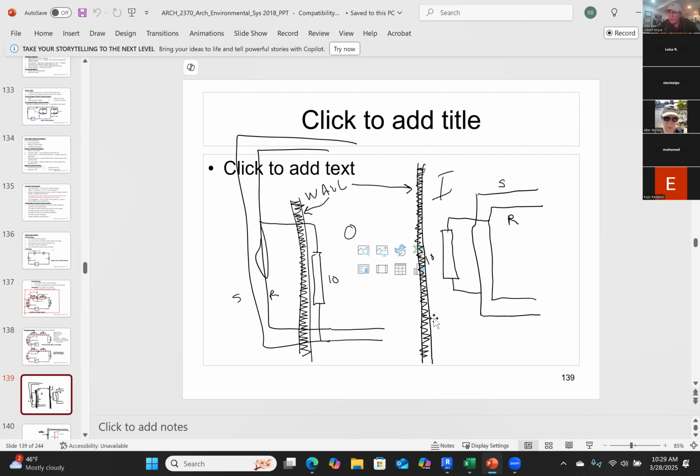It's quite often that the pipes run across the wall. Sometimes it runs in the floor. Sometimes it runs in the wall. In any event, for this class, it's schematic is fine. Just show me how you're getting the hot water from the supply line to the terminal unit, and, now this is a two-pipe system, how you are getting the return water back to the boiler.